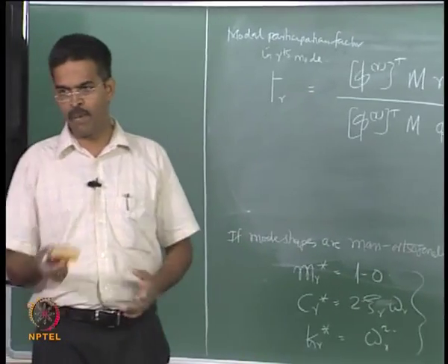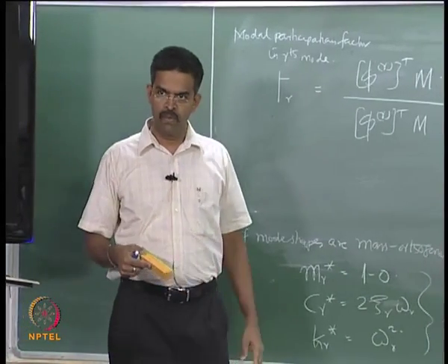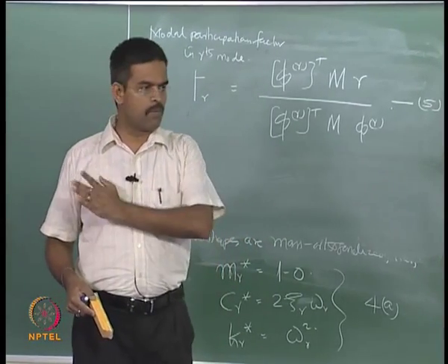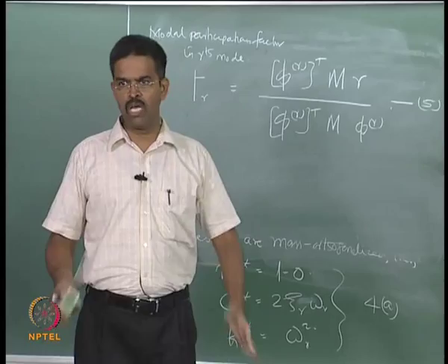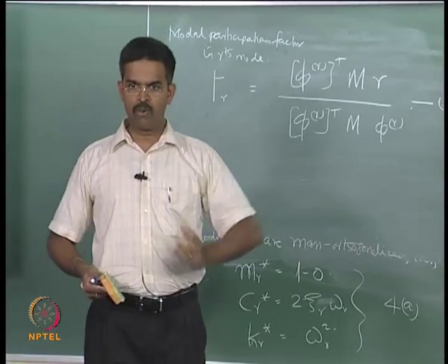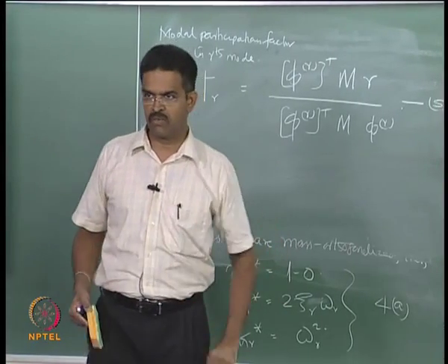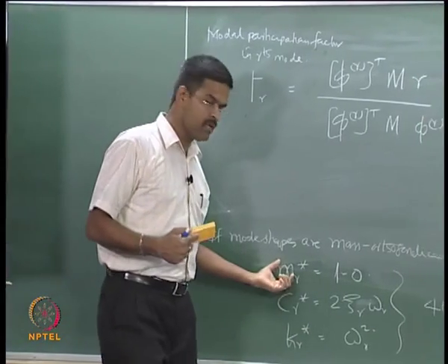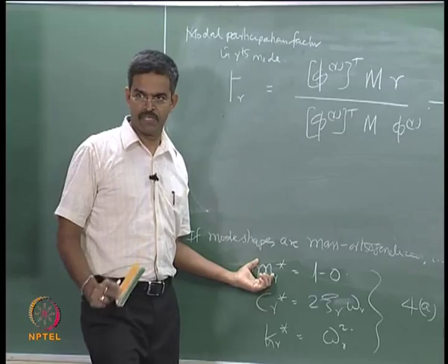For example, a paper floating: the motion of the paper is time variant, and the force I am blowing like wind is also variant. I do not do dynamic analysis to trace the response of the paper, because paper has no mass actually. The inertia component will remain significantly absent.